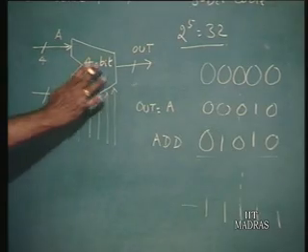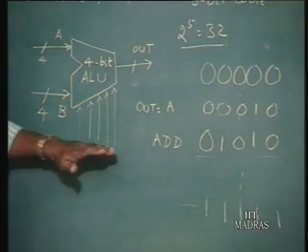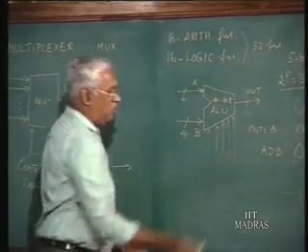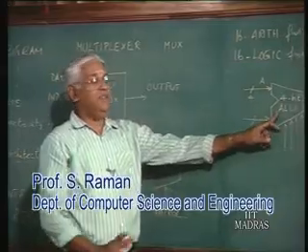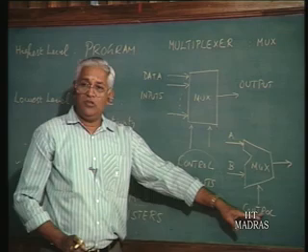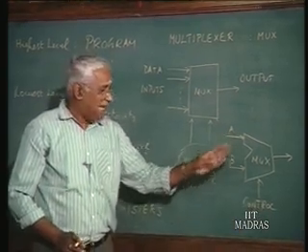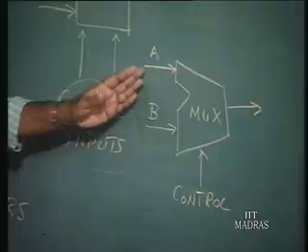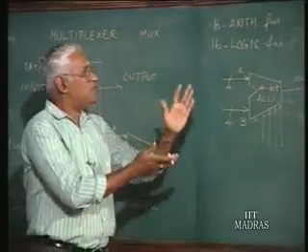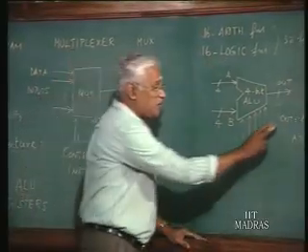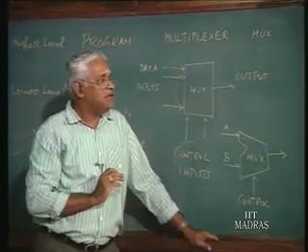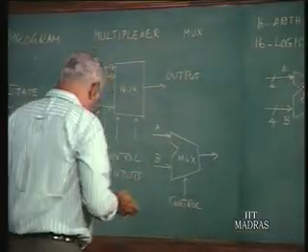So ALU, which is the heart of it, because it has 32 functions, will be getting a 5-bit code which will uniquely identify what this particular one is going to do. Similarly, the mux should have a control signal which will pass on A or B, just that. Now mux only passes on the data, whereas this ALU will be carrying out some function, arithmetic or logic, and can also pass on, as in this case. That is also one of the functions. It simply passes on, right? Okay, now that's about that.